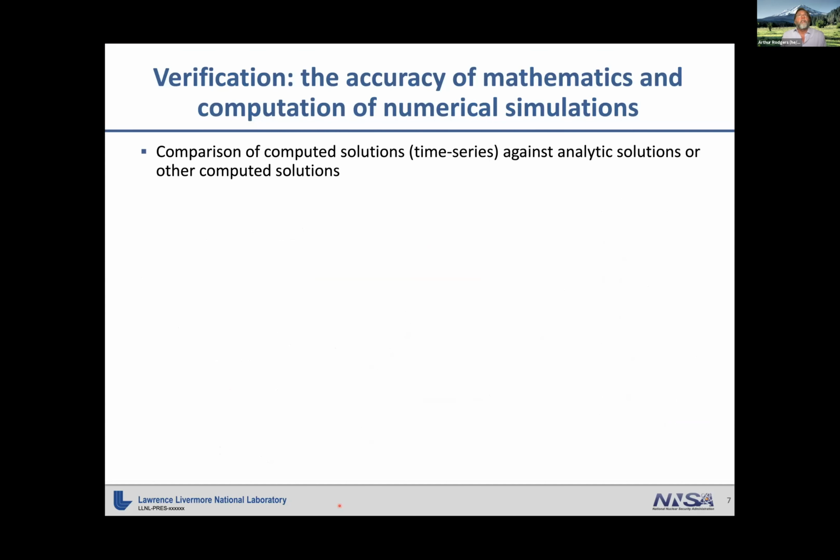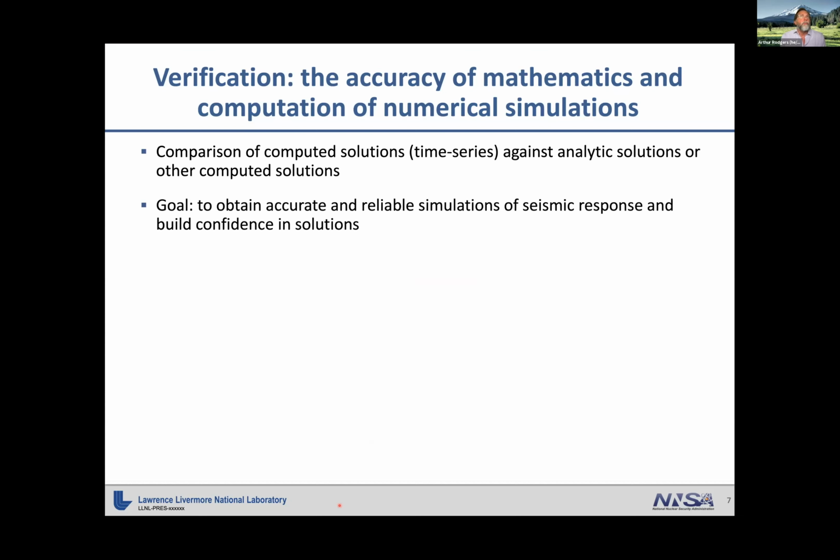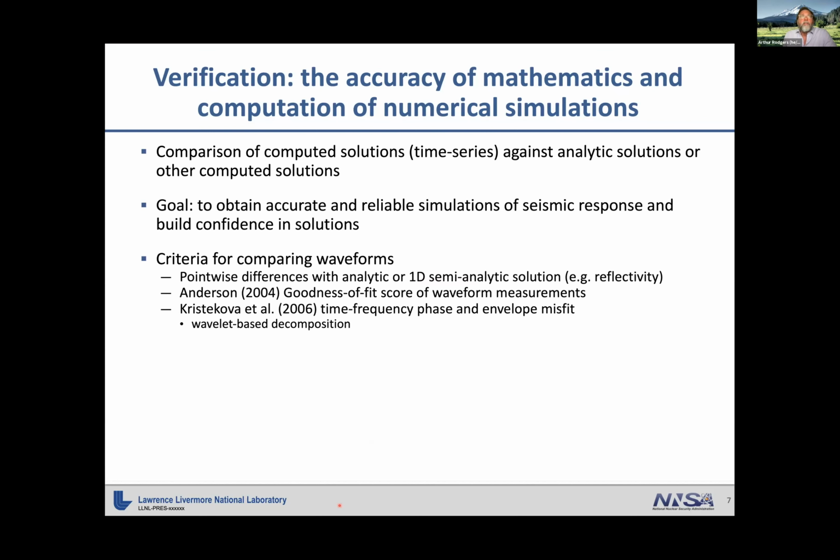All right, so verification is a mathematical and computational evaluation of the solutions to check their accuracy. And a comparison can be made of computed solutions against analytic solutions or other computed solutions. And the goal is to obtain accurate, reliable simulations of the seismic response to build confidence in the solutions. There are several criteria that people have used: point-wise differences between solutions, goodness of fit measures on waveform derived measurements, or time frequency phase envelope misfits have been used using wavelet decomposition.